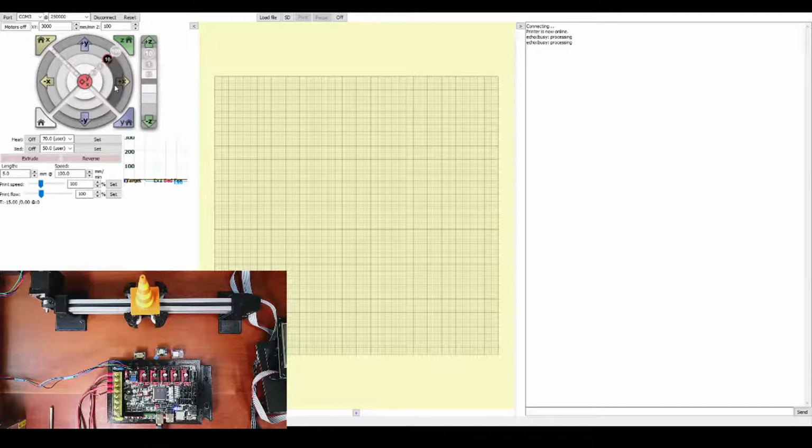There are other things that are more complex, but you're at the point where you're working with your actual print. So it's probably temperature related that your issue is, but there also looks to be a calibration issue. That's why the lines might be all over the place. So it could be related to your slice and how fast you said to move the printer when printing, or it could be a clogged print head and we don't know.